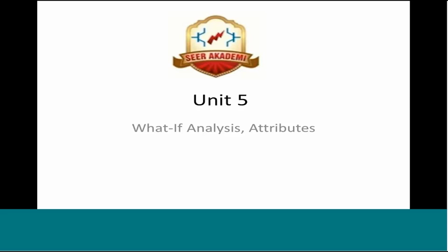Second, I will talk about attributes. Attributes is a very powerful feature in PrimeTime. So PrimeTime, as you're aware, supports the Tcl language. So attributes actually help. They enforce the Tcl language interface, reinforce it, and using attributes we can write very powerful procedures to get almost any kind of data that we want out of the design. Right.